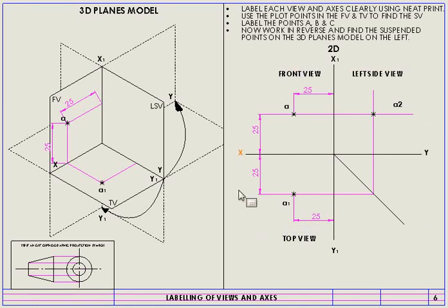Alright, now that we've found the left side view, front view and top view of this specific point, we're now going to carry this information across to this left side view. I've already given you guys the front view and top view, but let's discuss this in greater detail. If you look at my front view over here, I've already got 25 millimeters away from my x1, y1 axis.